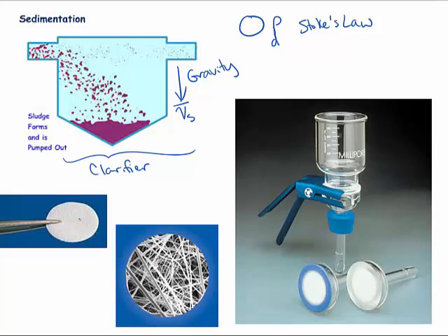Now, in environmental engineering, a suspended particle is defined explicitly as anything that can be filtered out by a glass fiber filter. And this is what a glass fiber filter looks like under a microscope. You'll see that it is just a collection of glass fibers. There is no exact particle size that settles on this, but there is a nominal pore size, which means an average pore size created by those filters that may vary, but typically is around 2 micrometers.